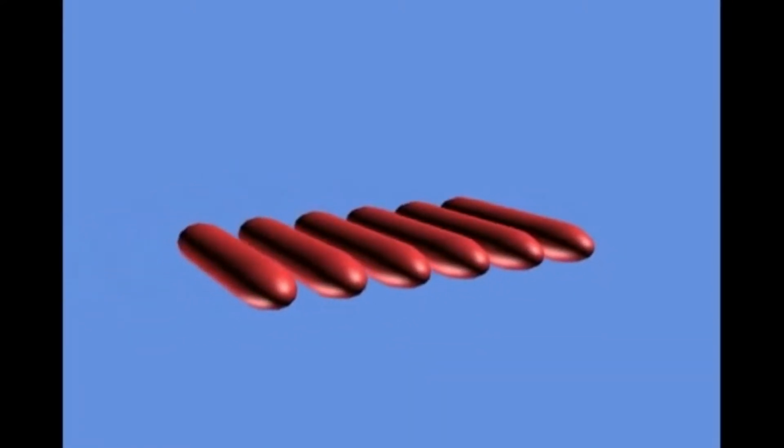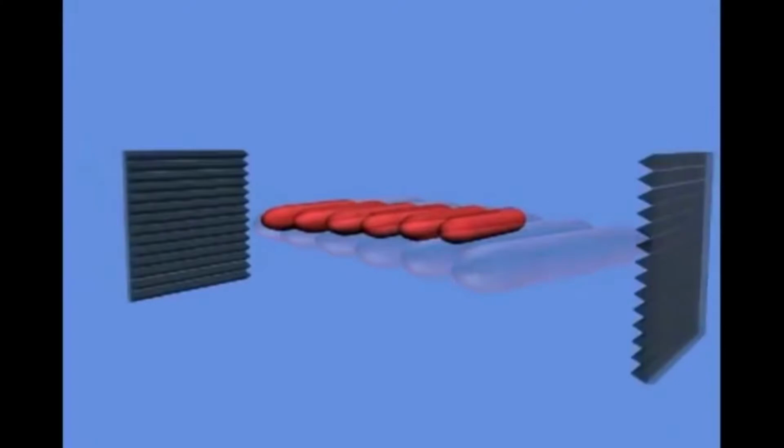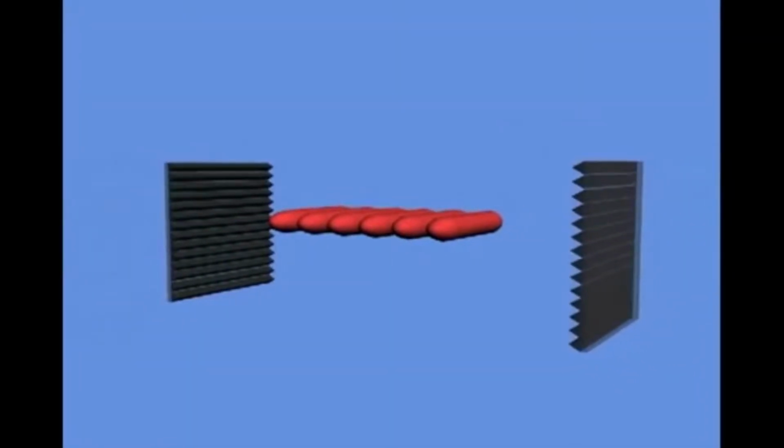Today's modern LCD technology is based on a discovery made by engineers Lehmann and Reinitzer around 120 years ago. Let's take a look at the technology in detail. In liquid crystals, the molecules are similar to long, drawn-out rods. As with crystalline structures, these molecules exhibit a strictly ordered crystal structure. The ordering of the molecules creates a directional orientation. In most LCD displays, the liquid crystals are embedded between two glass plates rotated by 90 degrees. This formation produces what is known as a twisted nematic LCD.